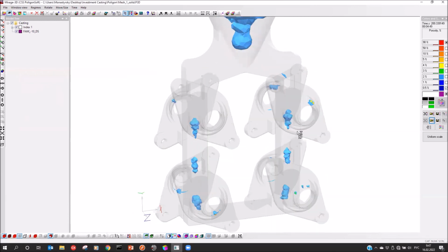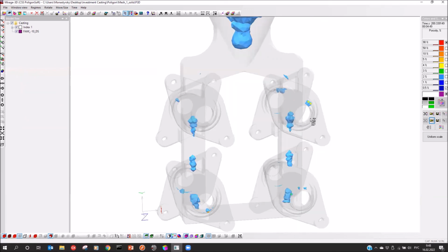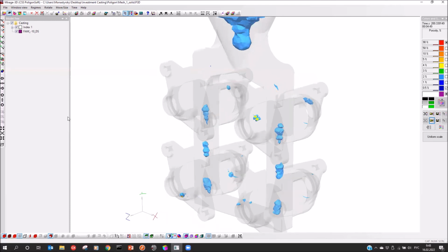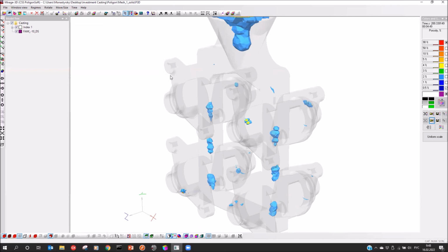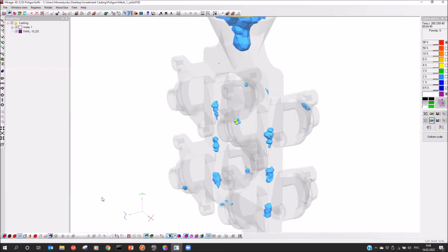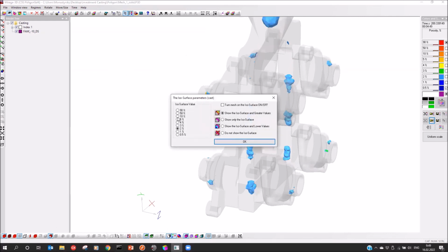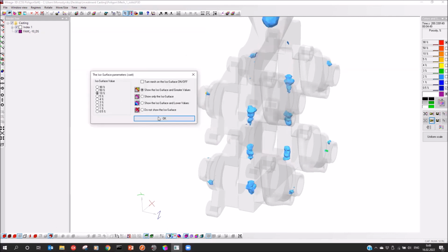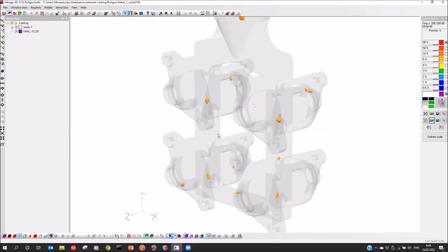And that's all. We don't see it. So microporosity is from 0.5 or lower percent till 2%. I think that for such a part with such thin walls, it's not a good situation. We need to do something to make these parts clear of porosity. And here we see porosity with a high percentage, and if I change here to 10%, we will see it. So it's very dangerous. I think it's something like small pipes. So we need to change the technology to avoid these problems.